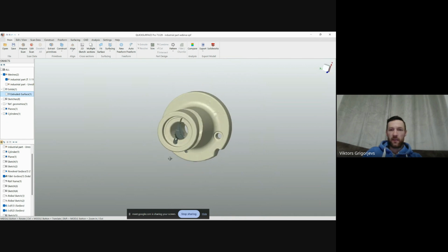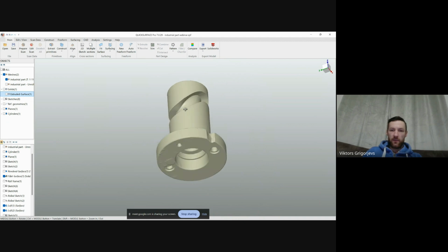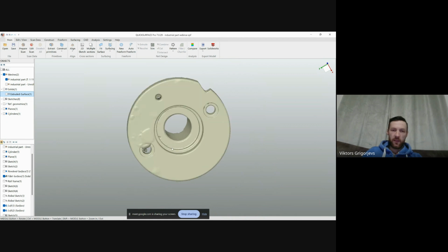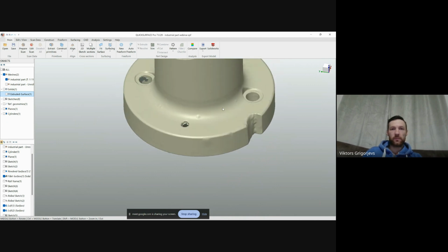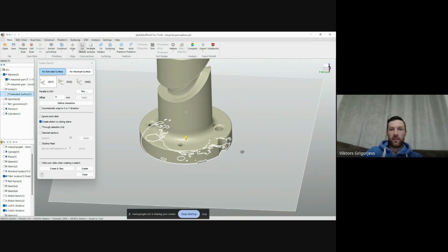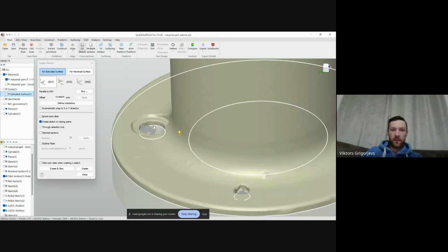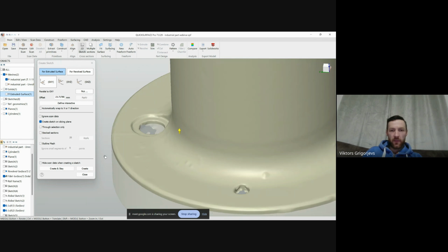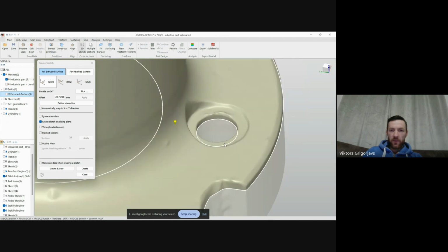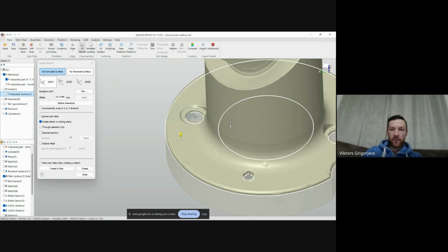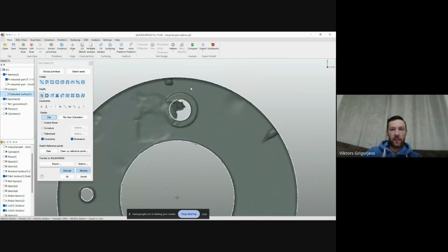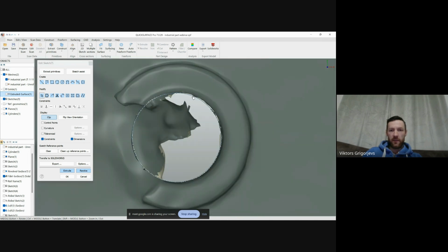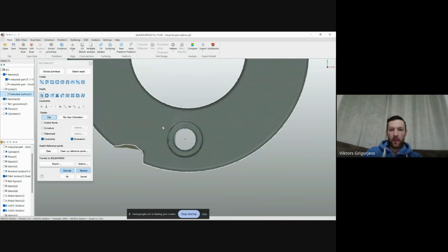And we choose the next. Inside we don't have anything. So, okay, let's create these mounting holes or whatever that is. Again, sketch based on top plane. Let's find out where we have some nice section of mesh for a cross-section sketch. I guess this one is good enough. And again, you can just hold your shift and drag around. It fits a circle automatically. Drag around here.